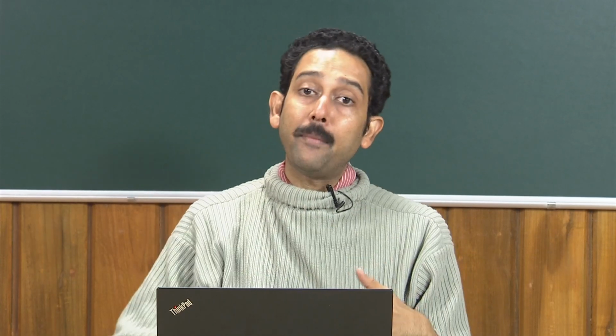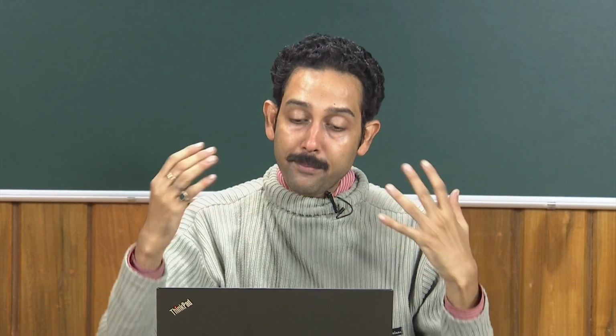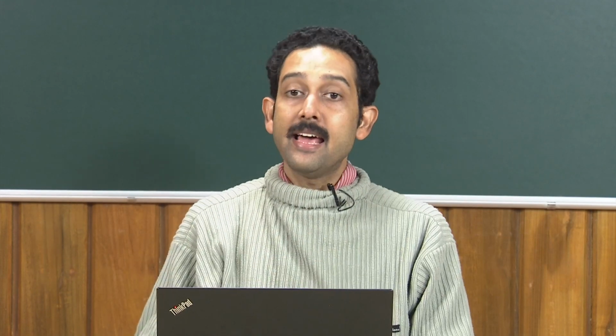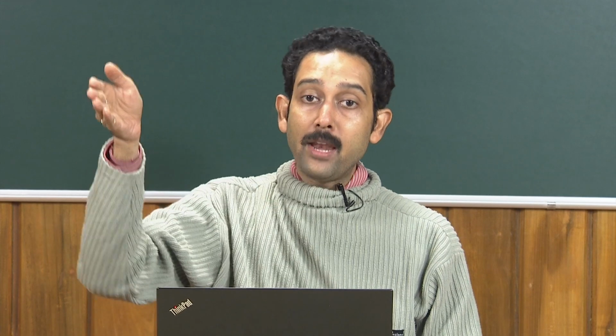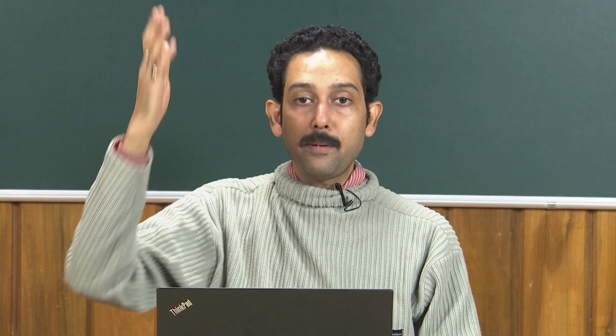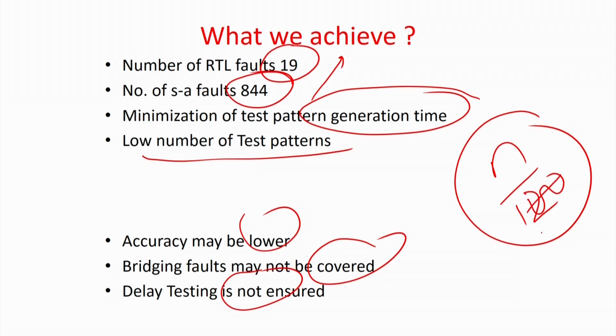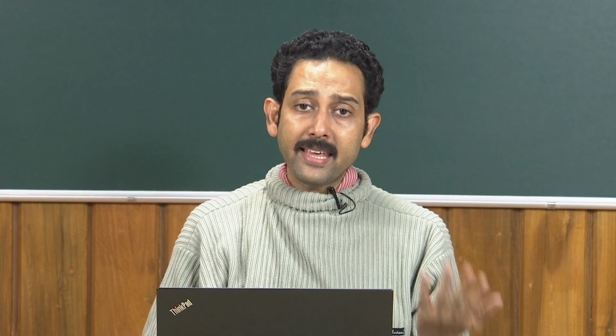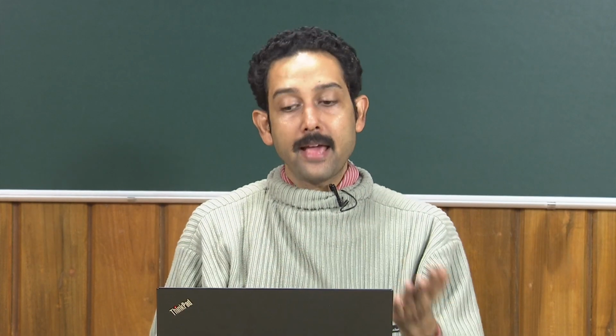But here also, if n is very large, the number of inputs, gates or nets is very high, then again you have to bring down the value of n. There is no other option other than to go for abstraction like RTL and RTL fault models. So even from 2n, we have brought it down to something like n by some tens of thousands. If n is 10 lakhs, at the block level it may be drastically brought down by the bit width, which may be 128 or 256. So the number of nets or gates comes down, and the number of test patterns and test time actually come down.